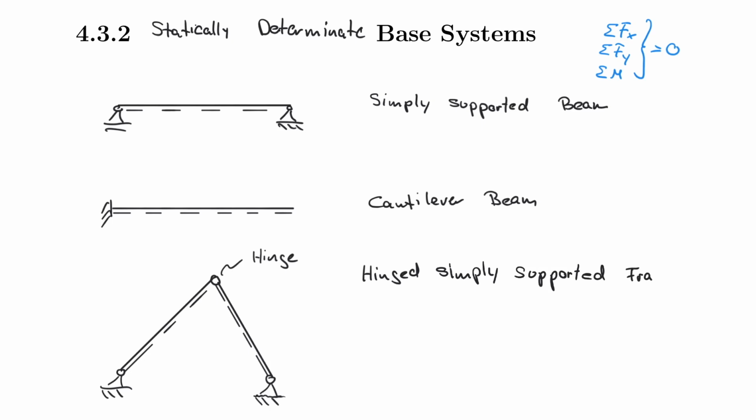And you understand where the name is coming from. So it's the simplest form of support to a frame that is hinged. Because as I said before, if I would have a different support reaction here, then this could slide out. Or if I make it more stable, it would just not be simply supported anymore. It would not be the simplest form. But the reason these 3 base systems are so important is because you can use them to form many other compound structures. And we will see that as well on the other page.